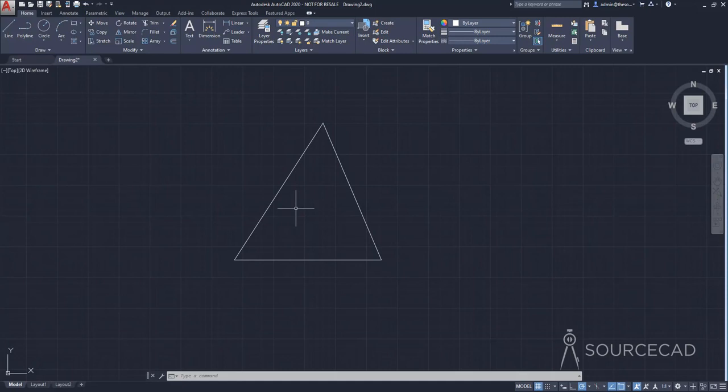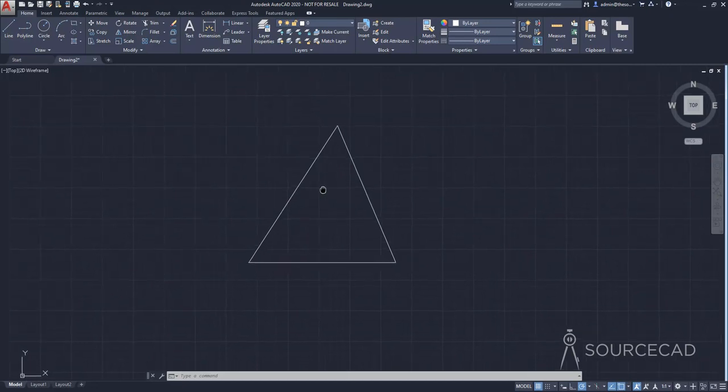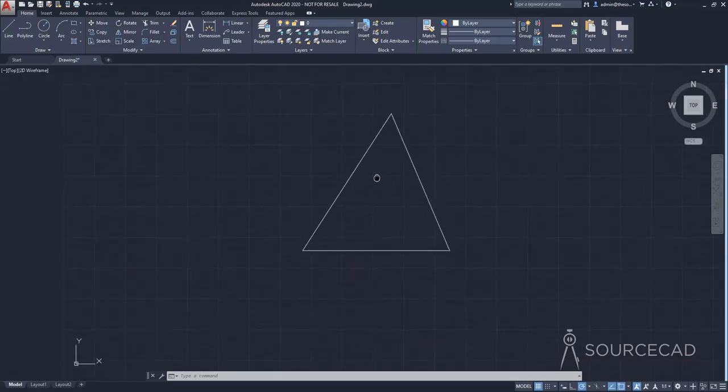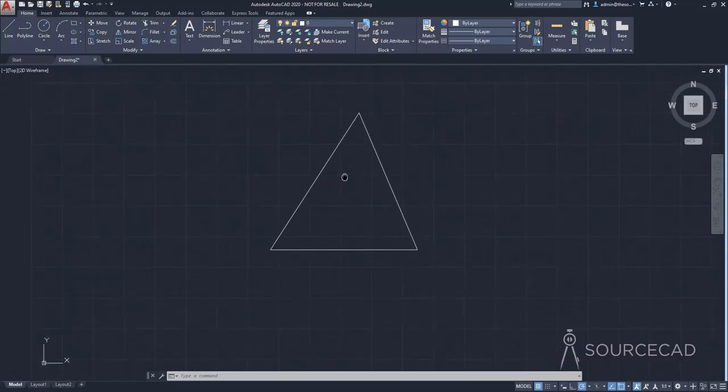So in AutoCAD, it is recommended to use a 3-button mouse, the left click, right click, and the middle mouse wheel. These buttons should be there, and to move this drawing, all you need to do is press and hold the middle mouse wheel. When you do that, your cursor will change to this hand icon. Now move your mouse and the whole drawing will move along with it. Don't let go of your mouse, just move it like this. Now let go of your mouse wheel, and if you move it, only your cursor will move now.